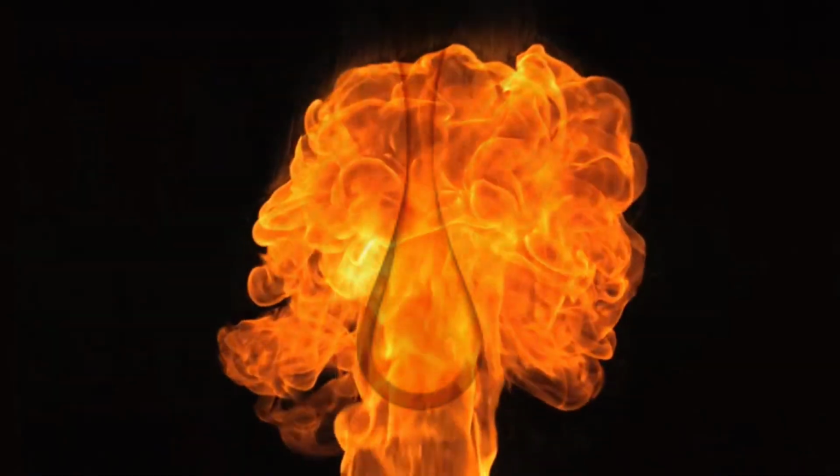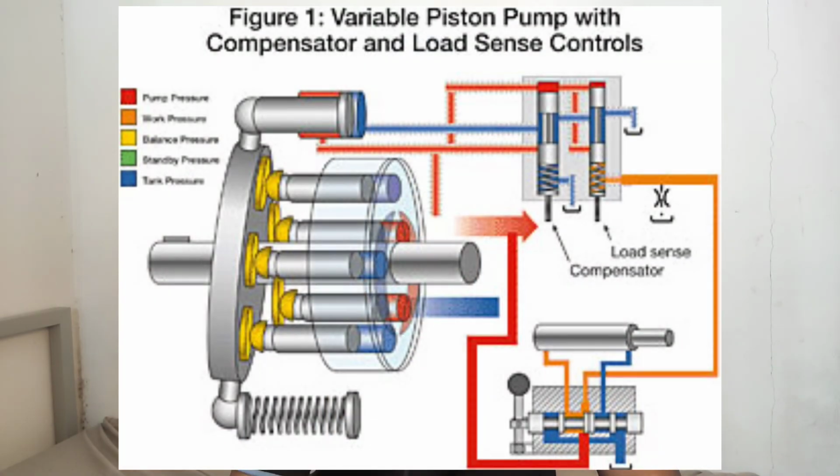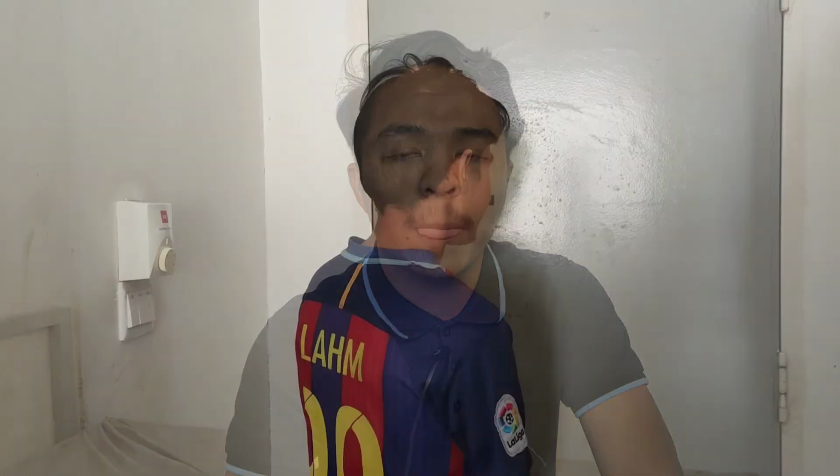Next, keep oil hot. Don't underestimate the value of a tank heater for industrial and mobile hydraulic systems. Cool oil causes cavitation, so warming oil prior to use is crucial.